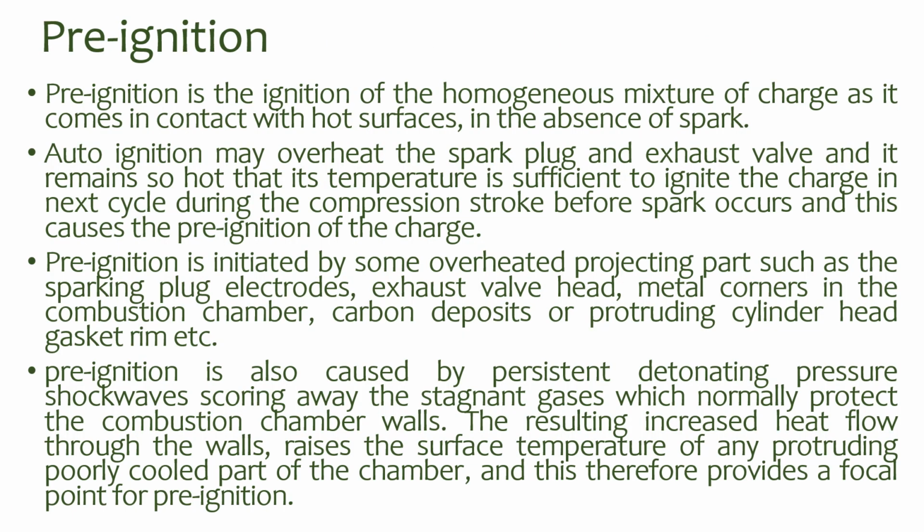Pre-ignition. Pre-ignition is the ignition of the homogeneous mixture of the charge as it comes in contact with hot surfaces in the absence of a spark. Auto-ignition may overheat the spark plug and the exhaust valve, and they remain so hot that their temperature is sufficient to ignite the charge in the next cycle during the compression stroke before the spark occurs, and this causes the pre-ignition of the charge.